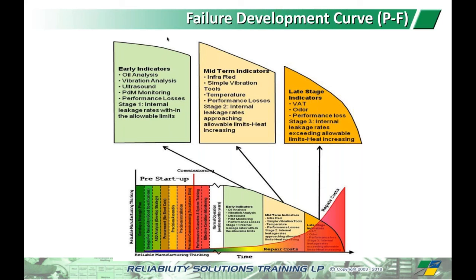It's possible, it just takes a lot of work, but I tell you, ultrasound here is a really, really good tool in a lot of different ways. And again, towards the end of this presentation, I've got some examples of that and some applications of it I think is really, really powerful. I guess the point I'm trying to make is condition monitoring is possible to do on hydraulic systems. Okay, we don't have to just run them to failure. We can do condition monitoring.